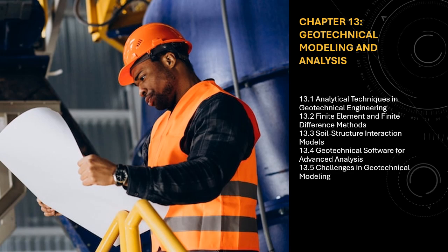1. Soil stiffness. This defines the soil's resistance to deformation under applied loads. It can be represented by parameters like the modulus of elasticity, shear modulus, and Poisson's ratio. 2. Foundation compliance. The flexibility of the foundation or base of the structure, which can be modeled as a spring with specific stiffness in different directions.